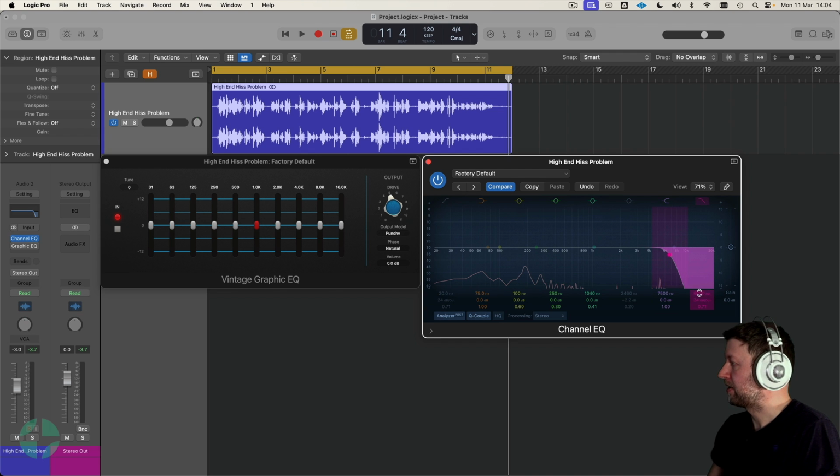And so this number tells us at what point the EQ is being applied. So in this case, everything around 6,700 and above is going to be gradually rolled off according to the curve that we set here. It's a little bit more advanced than you need to know, but there are different curve shapes, with lower values having a more gentle curve and higher values having a steeper curve.